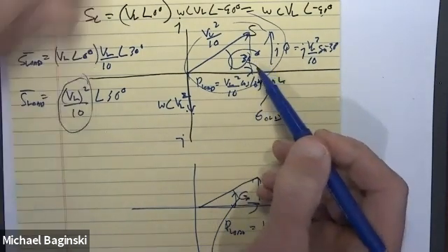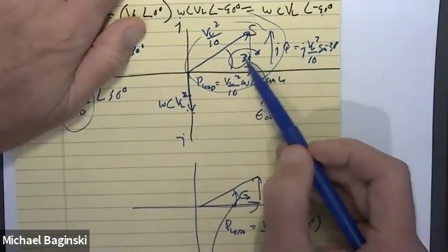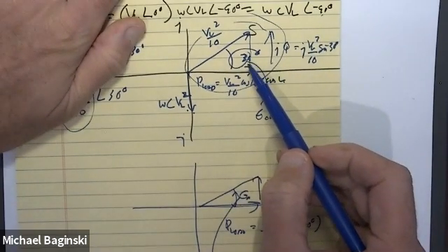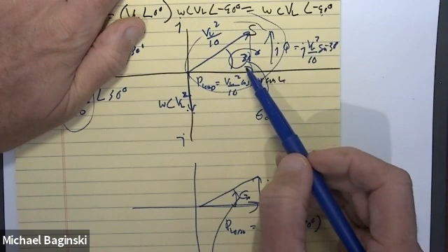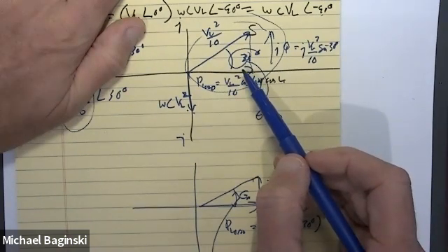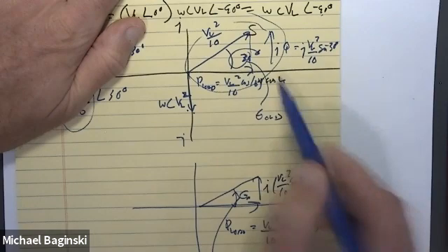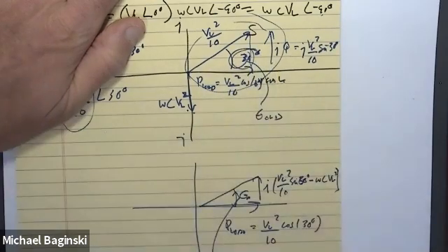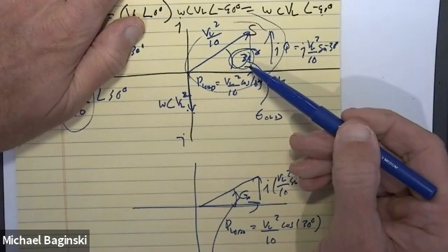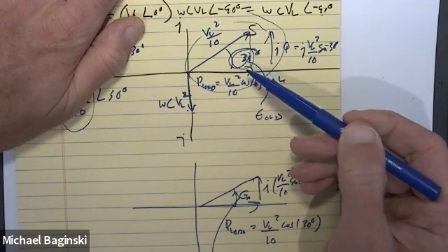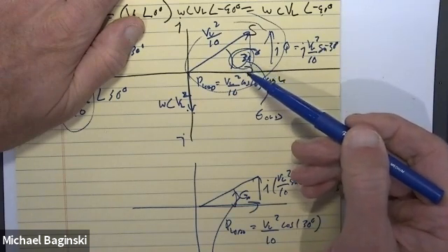When I looked at this, before I added the capacitor, if I wanted to know what the power factor of this load was, now hear me, I didn't say this prior. Once I have the complex power, if I just take the cosine of the angle, when you plot them right there, that is the power factor. Do y'all hear me? Now, it's implied that you already know that because you're going to have the current and take the conjugate of the current and multiply it by the voltage. But this is the original power factor, the cosine of 30 degrees, which is what, 0.866, something like that?